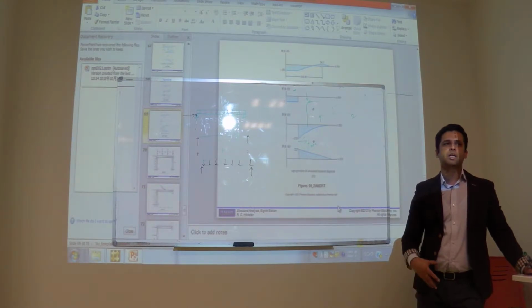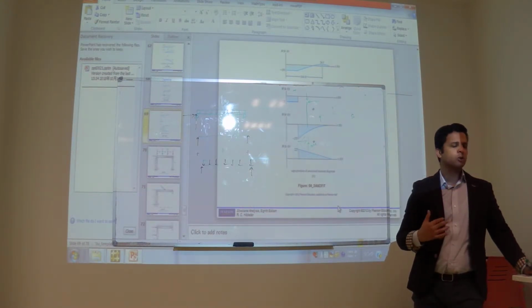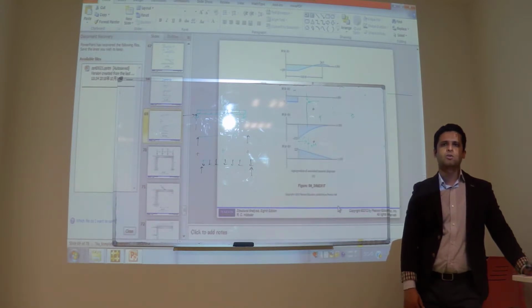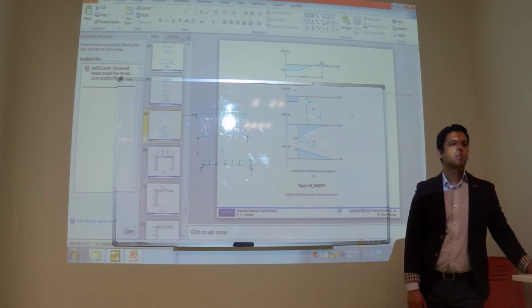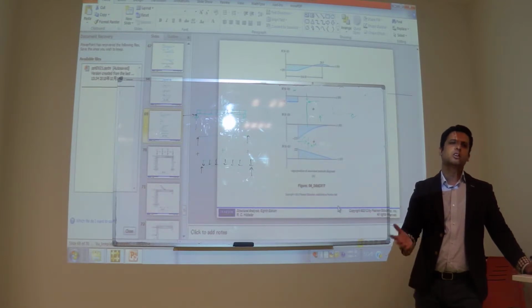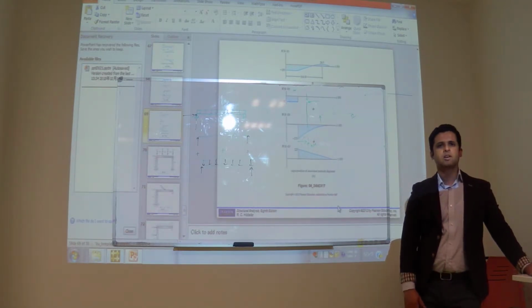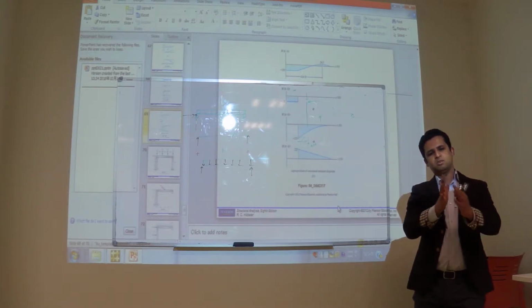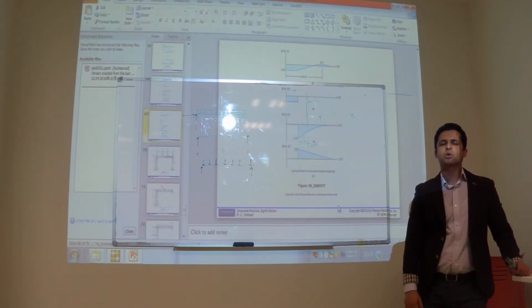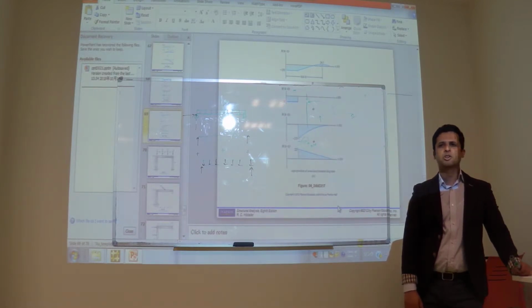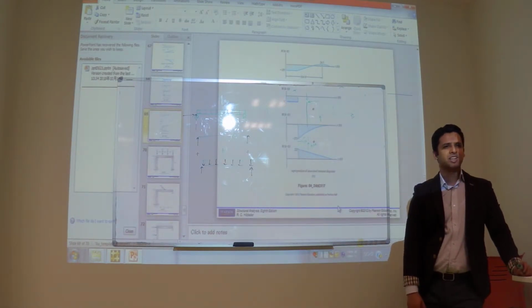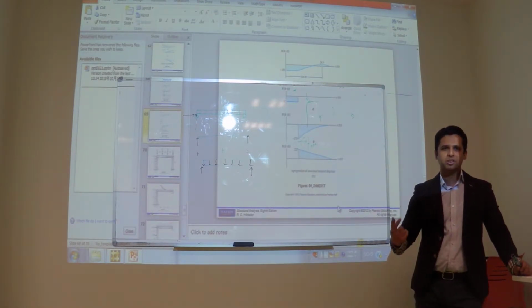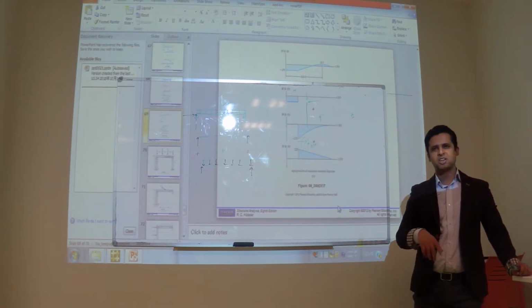If your material becomes non-linear, non-elastic, then I think you cannot use this for design or for analysis. Then you should use another method. If it is before cracking, you can use the finite element method. If it is cracked and separated, you can use the applied element method or the distinct element method, which is beyond your scope. That is researchers' territory, and I don't want you to go there right now.